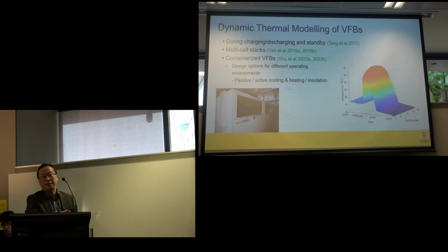And recently we worked on the containerized flow batteries, looking at the thermal modeling and using that model to analyze the design options for different operating environments, looking at the options that we need: passive or active cooling, heating, or insulation.